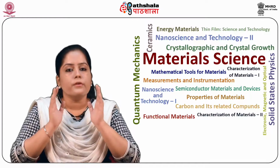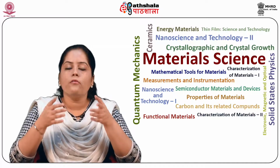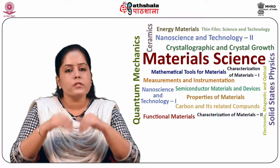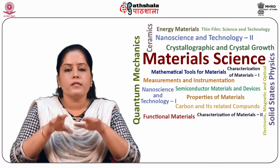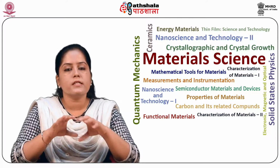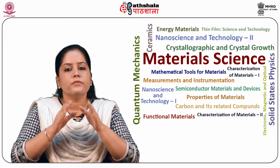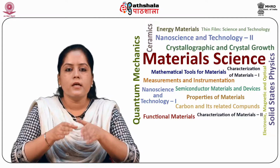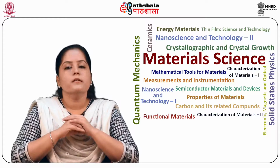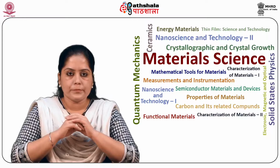In the case of the recess gate structure, a new layer of N-type gallium arsenide is introduced to fabricate the drain and source contacts, and selected areas are etched. So the thickness of the layer under the gate is highly important in deciding the threshold voltage of the FET.